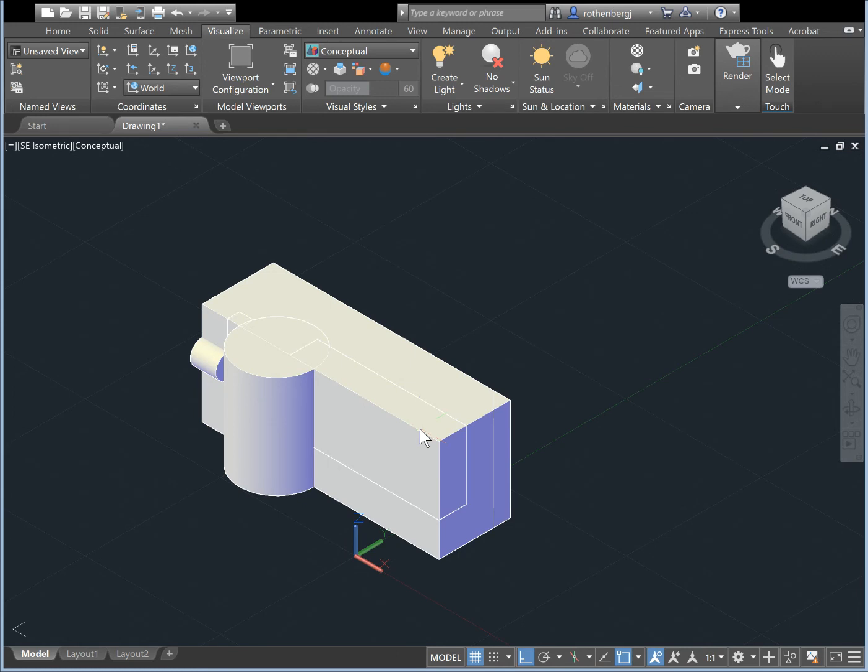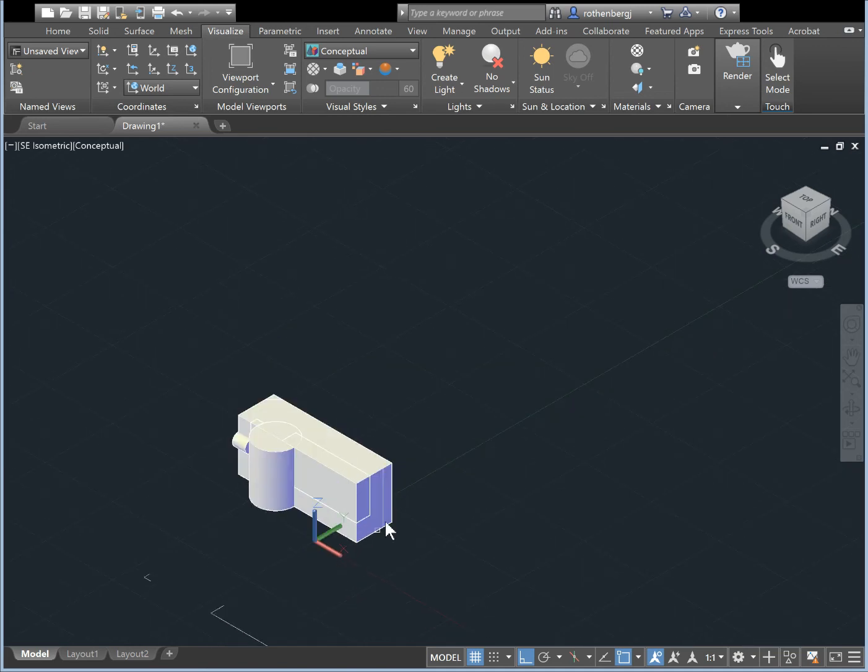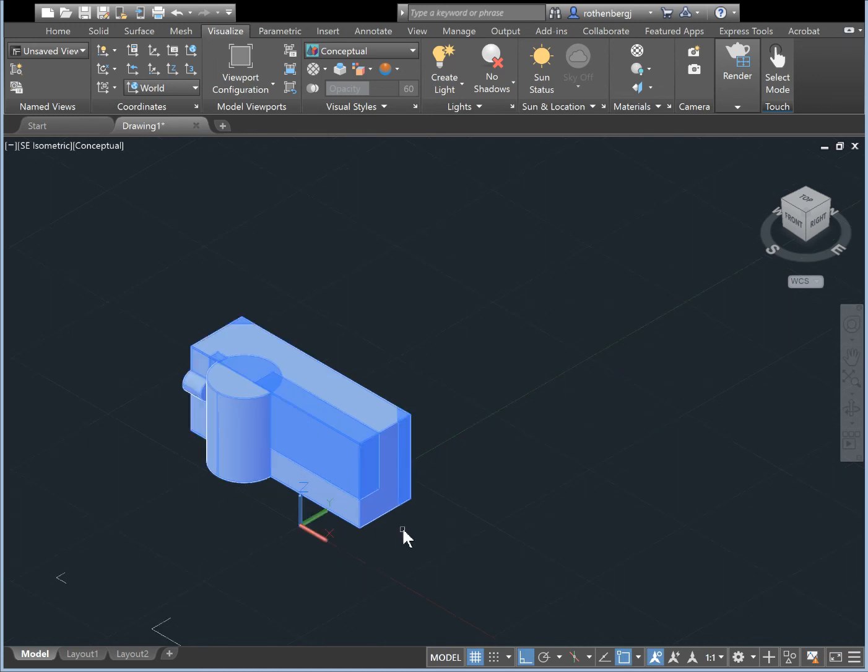So enter the subtract tool, subtract. Now select the main body, nothing else, and hit enter. Now, here's a trick. We could select everything besides the main body. So we're going to be selecting all the 3D solids in this area, and then hold down the shift key and select the main body again. This will deselect the main body. So now everything is selected besides the main body. And hit enter. So now our 3D solid is done.